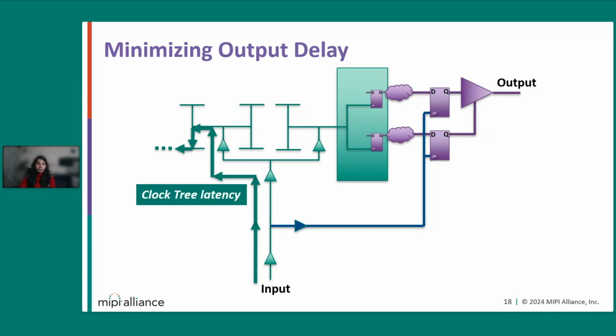And this is the green part. So this green highlighted zone is the main clock tree of your design. And that will be the clock tree which includes the clock tree insertion delay in the output path. But you can have another wire that will branch out from the clock tree input side of the design that will drive the final output register. And how will we do that?